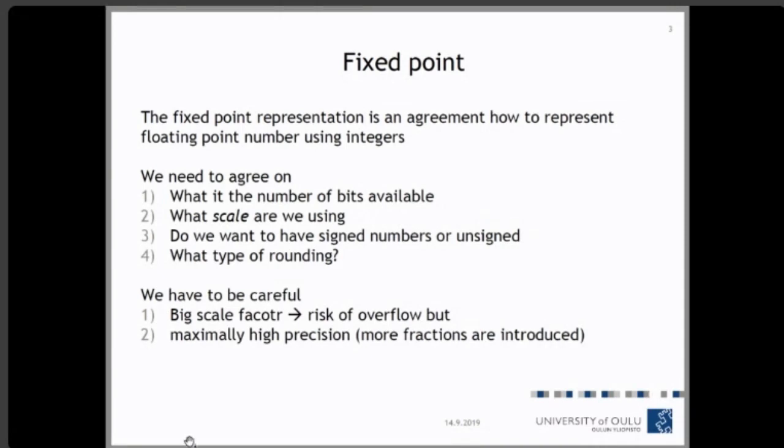So we saw that fixed point had multiple advantages: it simplifies the design in terms of hardware resources and power resources, and helps to add performance because it is entirely based on regular integer operations. But the programmer should take care of numerical errors that may arise due to fixed point operations, which are overflow and underflow.